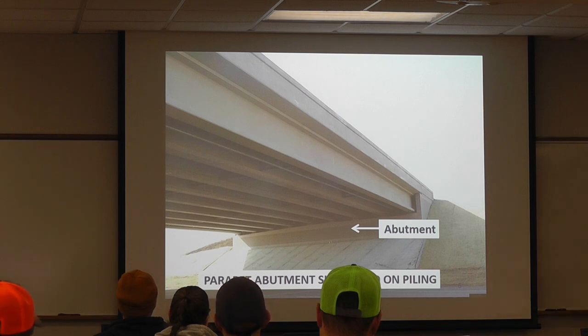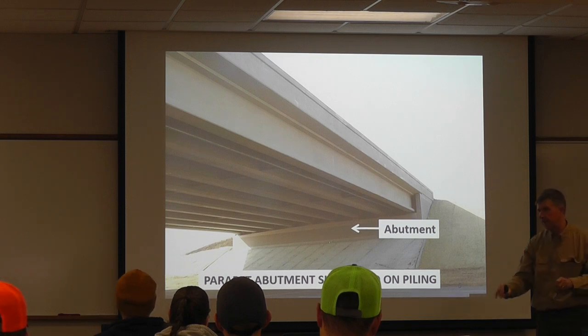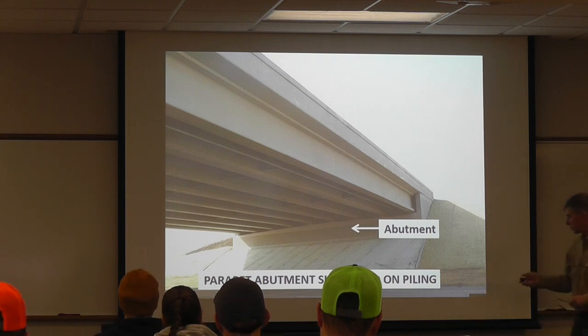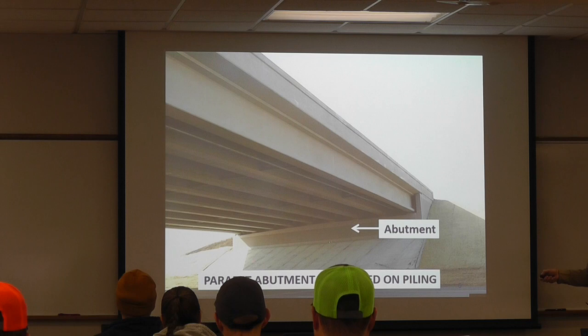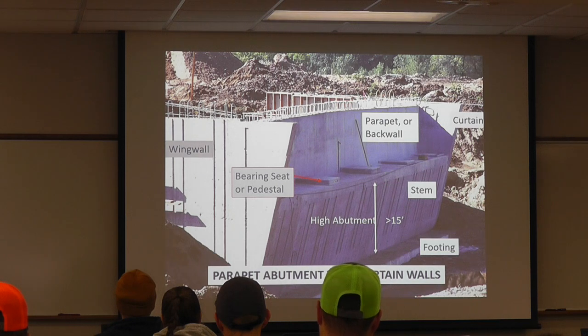It's a kind of a top-down construction. You excavate maybe 5 feet, put some soil anchors back in, put a shotcrete facing on there, and then go down 3 more feet and put in some anchors and shotcrete, and eventually you end up with, you know, maybe an 8 or 10 foot high wall right here, enabling you to get one more lane of traffic. So that's been done at times.